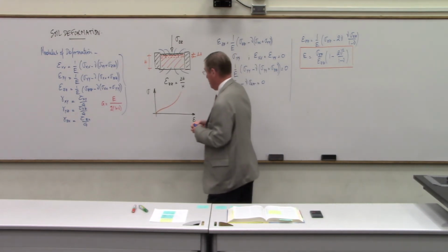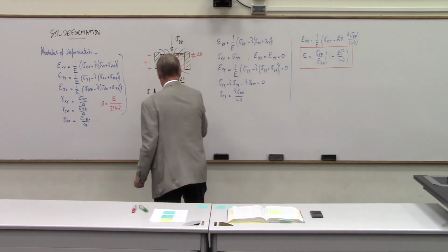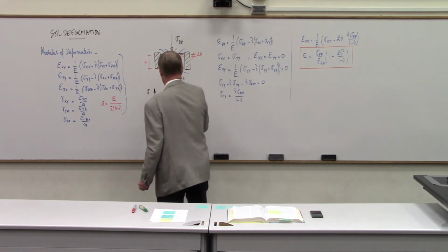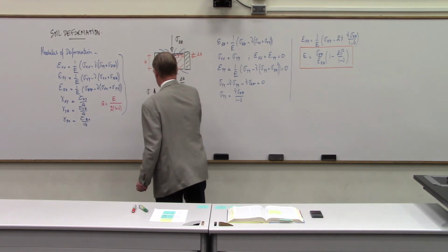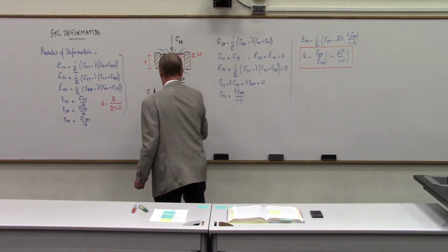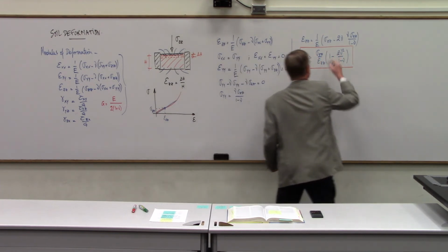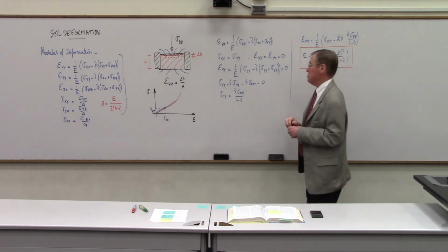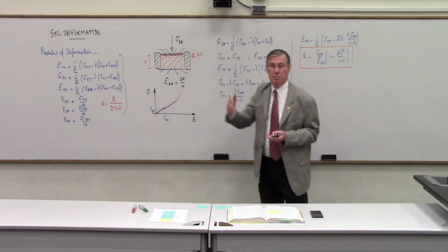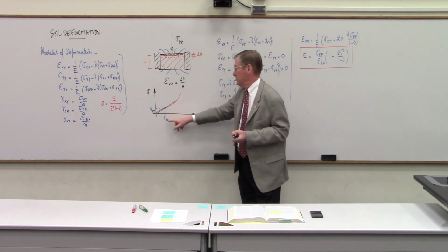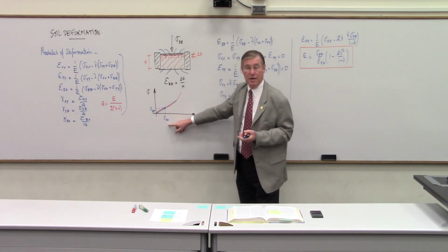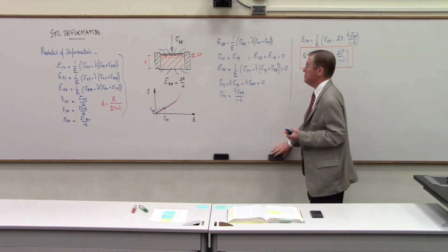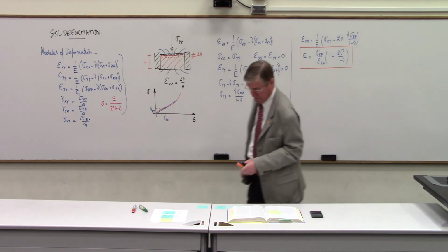But you could take a point on that curve, put a straight line on it, and you would have a sigma ZZ and an epsilon ZZ. You estimate nu at 0.3 to 0.35 for the drained Poisson's ratio, and from this test you can get a modulus. Again, you have to be careful to be at the right value of epsilon.